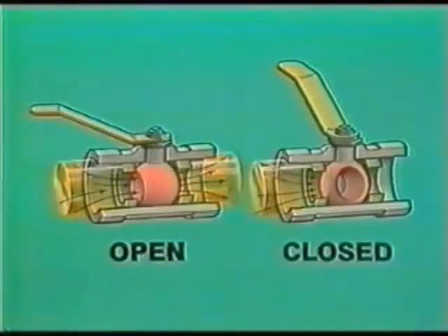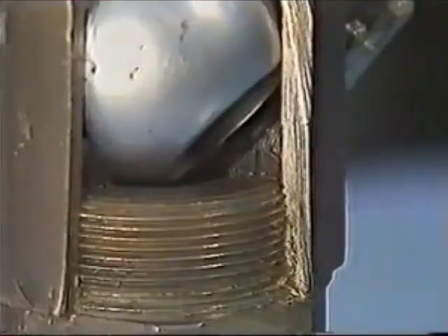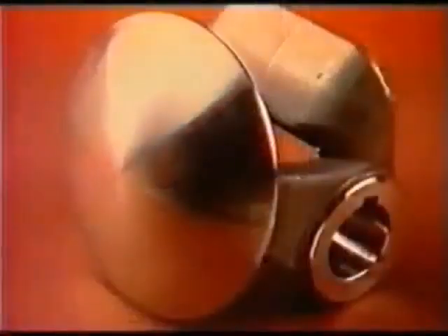Ball valves are primarily for on-off service. In the throttling position, high fluid velocity will rapidly erode the partially exposed seat ring and the edge of the port opening. A ball valve, however, can be adapted with a special plug that makes throttling service possible.